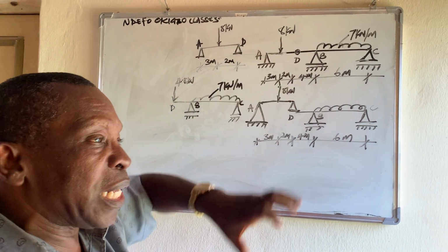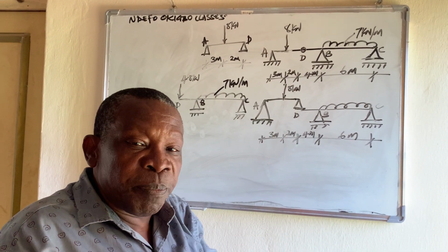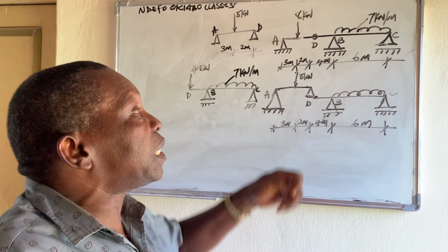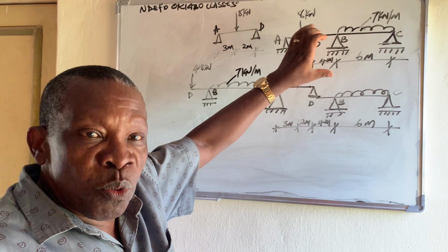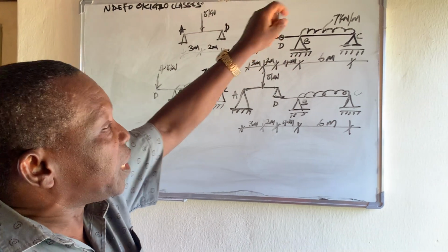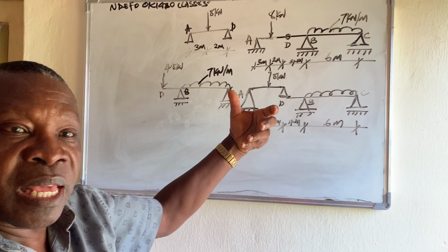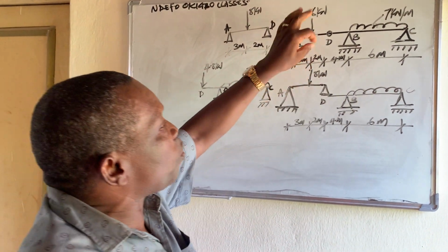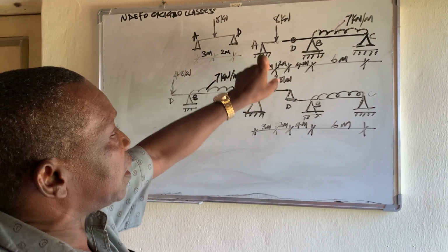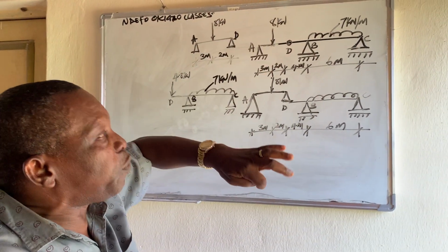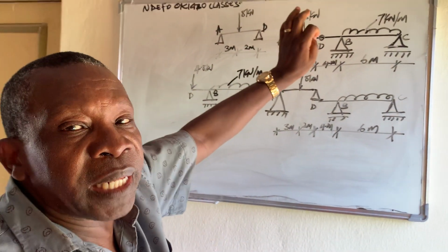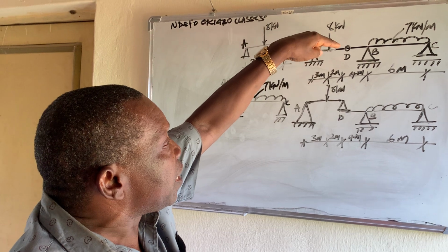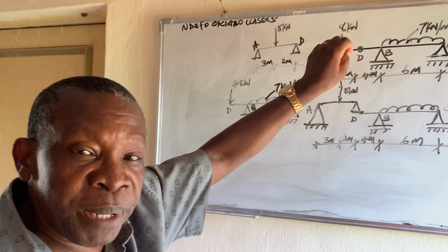What do we mean by flexibility? At the point of flexibility, it's no longer rigid as other points. It's no longer stiff. That means it cannot resist bending moment. It will bend if bent. Other areas will resist. That means a stress factor has been removed from that point. That's a bending moment. That's what would have made the beam indeterminate, but for the fact that the hinge removed that factor, because the hinge introduced flexibility at that point.